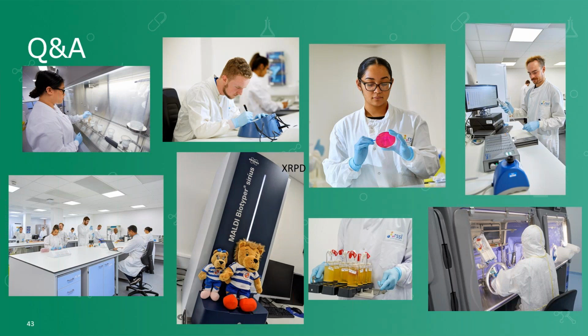So it was some engineering work, and the standard protocol was that after the work had been done, that part of the subloop was supposed to be flushed to drain. So you'd reduce any contamination present by flushing with copious amounts of the clean water. But on this occasion, it was reconnected and wasn't flushed, so contamination had entered,